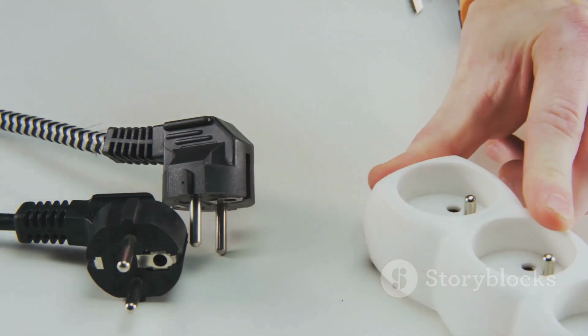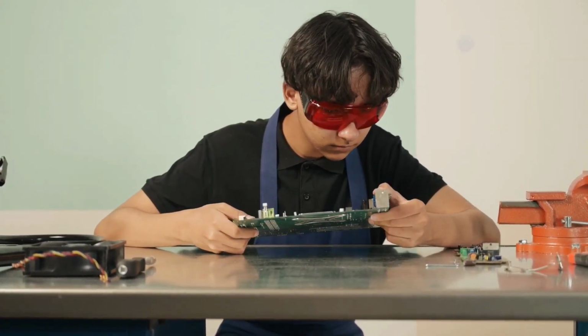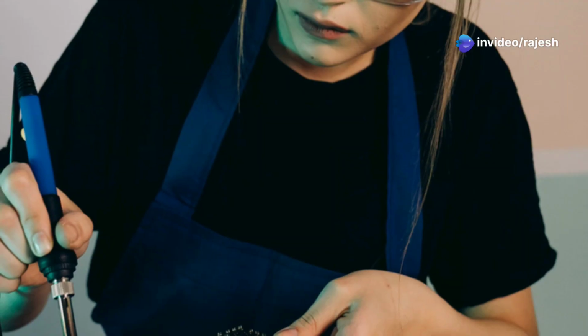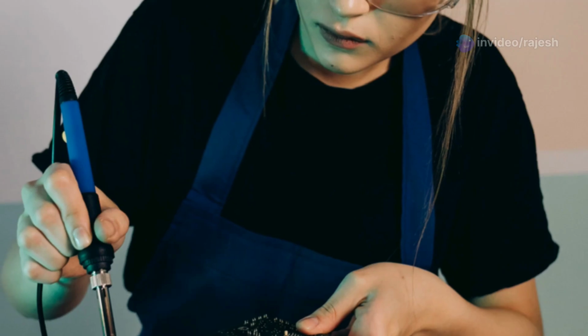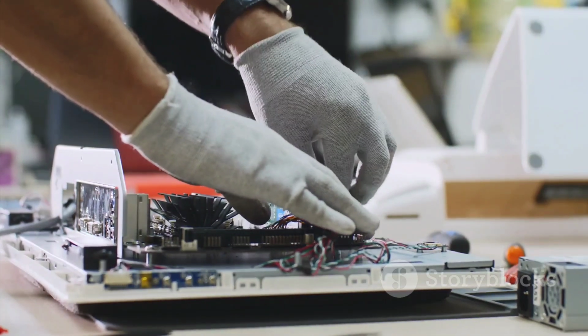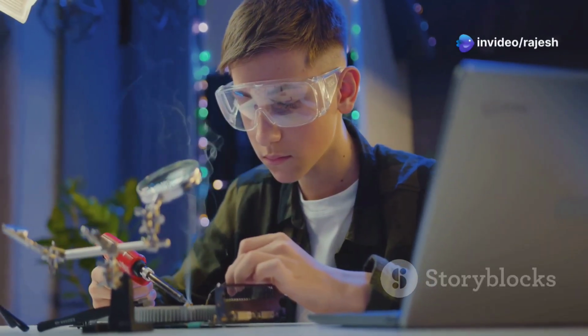Use insulated tools. When working with live circuits, use insulated tools like pliers and screwdrivers to prevent electric shocks. Wear safety glasses. Protect your eyes from flying debris when soldering or working with components that can shatter. Avoid touching components. Some electronic components can get very hot during operation. Avoid touching them directly to prevent burns.